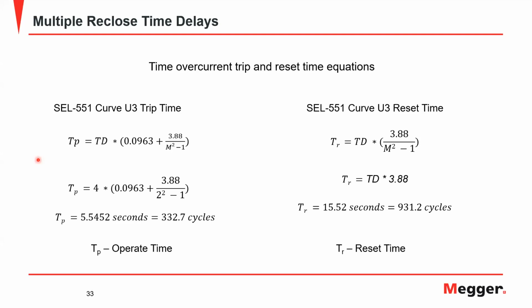Now, electromechanical relays have a feature, which is that they trip in one curve and they return or drop out on another. And that is something that can make it a little bit challenging to coordinate. So it's better to use, with the ability that we have today, a computer program to do the coordination rather than relying on hard and fast rules of using this many cycles and things like that.